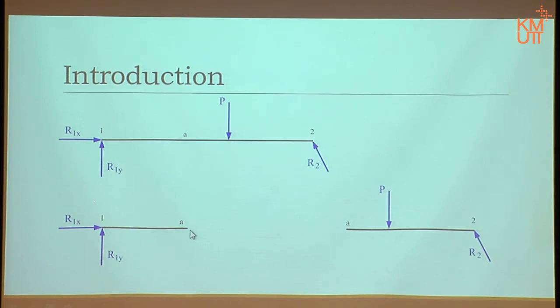Therefore there must be forces here acting on it. I haven't drawn it yet. This part is the same, meaning from here to here is the body. If we look at this picture, then we consider this part the environment. The contact between the body and the environment is at point A, so there must be forces here. Don't forget that we always say the reaction comes from the condition of the contact.